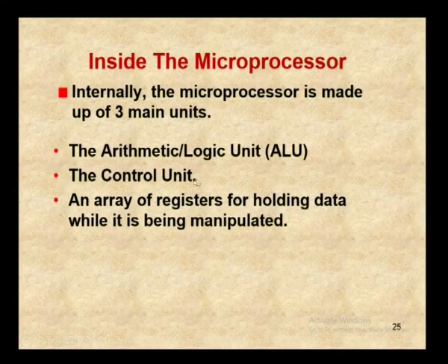It has to decode the instruction and tell the arithmetic logic unit whether to add or subtract or shift or multiply and so on. So, the control unit generates all the control signals. It has to tell when to read the memory, when to send the data to the output unit and all those things. And then it also contains a little amount of memory inside the processor itself.